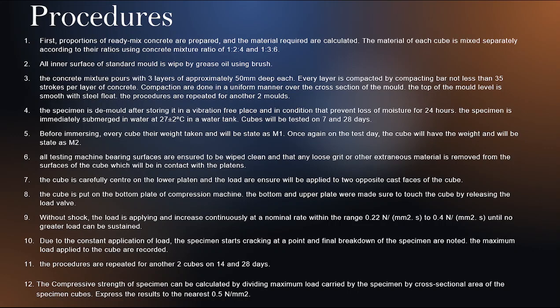24 hours. The specimen is immediately submerged in water at 27 plus or minus 2 degrees Celsius in a water tank. The cubes will be tested on day 7 and day 28 after submerging. Before immersing, all cubes have their weight taken, stated as M1. And once again on the test day, the cube will have its weight taken, stated as M2.